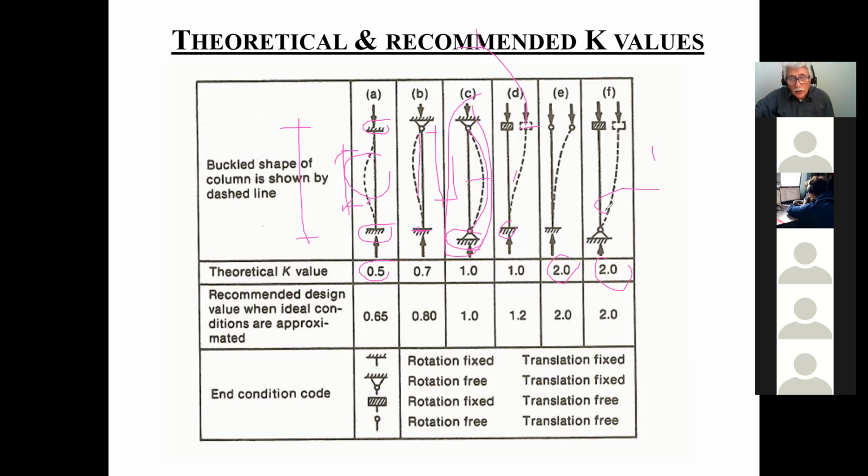Okay, so these are, like I said, just graphical representations of how you're preventing the movement at the reaction area, at the connections. This means I allow no translation, no movement in X, no movement in Y, and on top of that, I don't allow this to actually rotate about that point. That's what we mean by fixed, that there are no degrees of freedom. You can't rotate, you can't move this way, and you can't move that way.